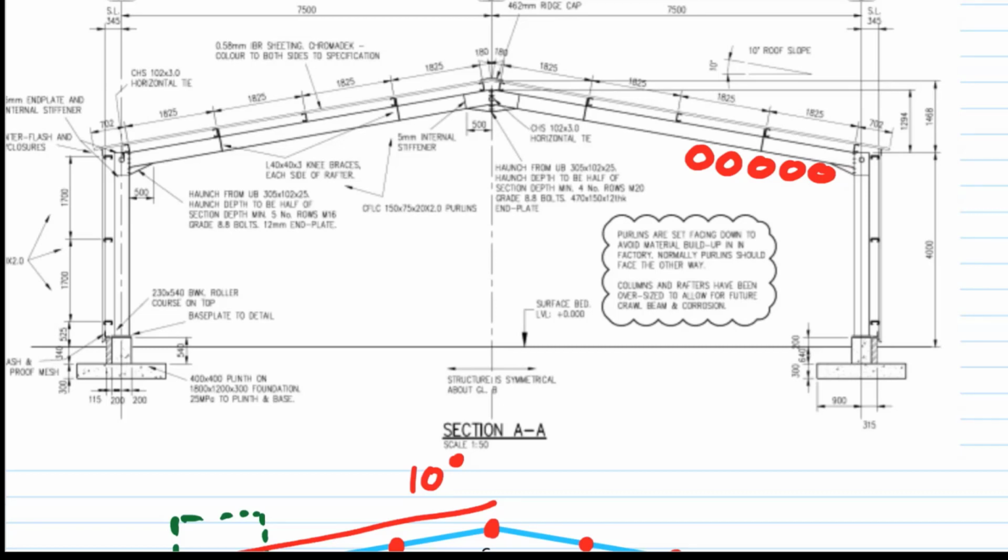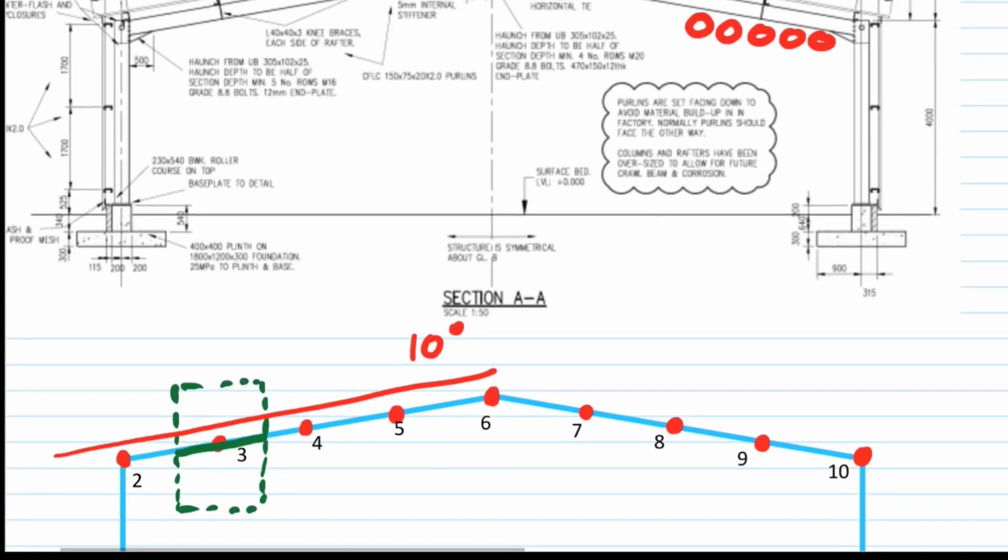However, in a formal building where the services are pipes and sprinklers and the likes that are relatively constant, unlikely to change much in the life of the building, you should be taking them as permanent loads. But this does highlight how you often need to apply engineering judgment and say what would happen in the future and what is the most conservative but realistic load, and then go with that. You may not need to just blindly follow the code.